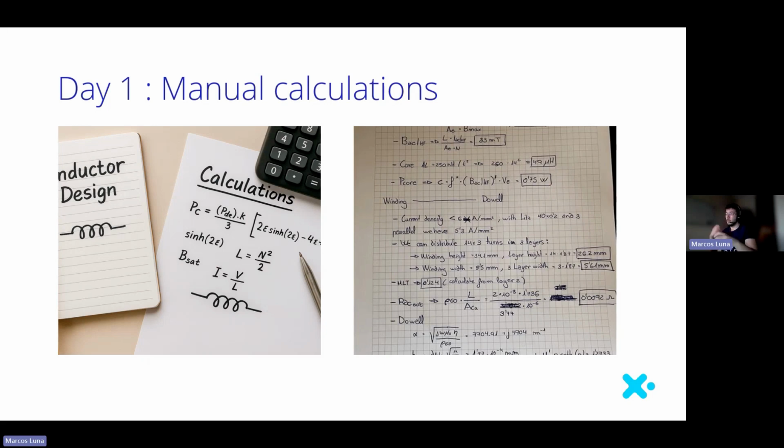He started a calculation with the round wire, and he realized that with round wire, RDC is very fine. It's very small. But then there are other losses that need to be considered here, which are the RAC losses, or the AC losses, sorry. So he found an approach made by Dowell in the past, okay, with some equations that depend on the distribution of the layers and also the wire diameter that you have.